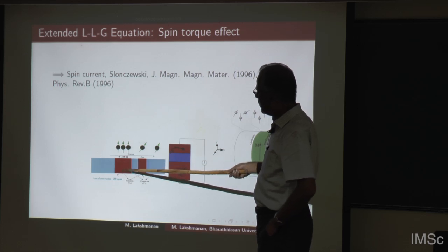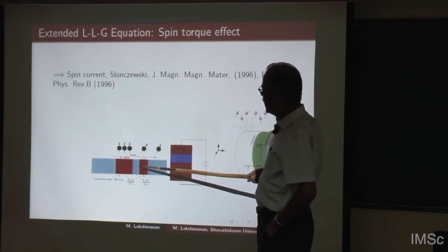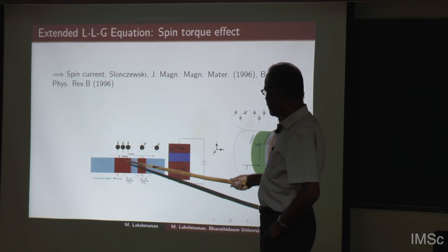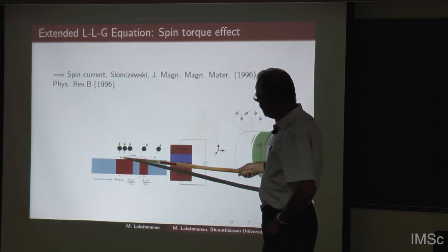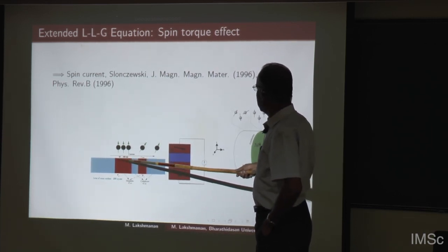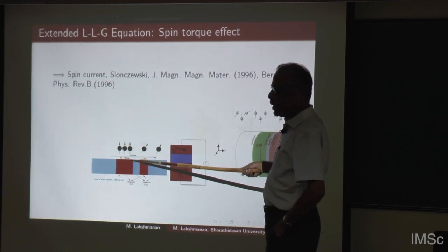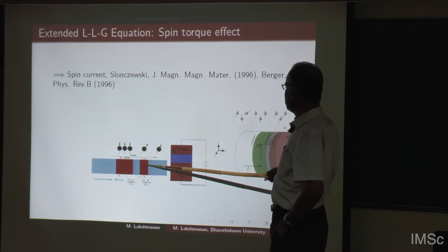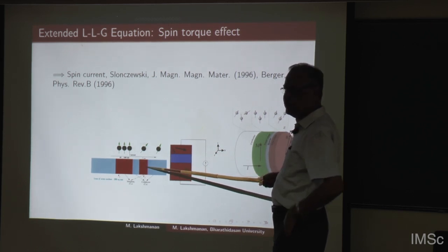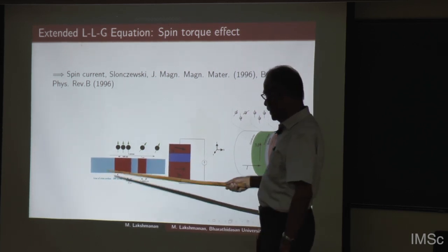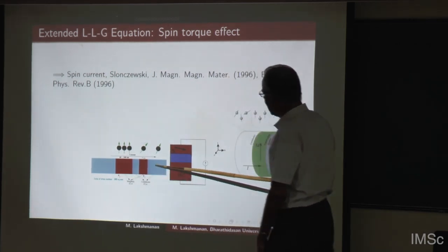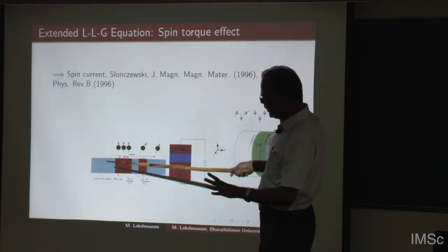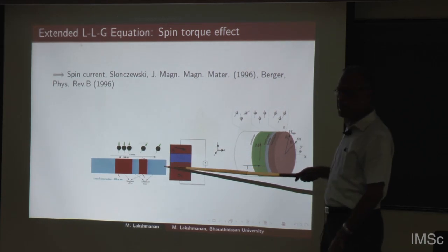So, you have cobalt, copper, cobalt, and this is a nanomaterial of the order of 40 to 100 nanometers, and this is again a small spacer, of the order of 2 to 4 nanometers film size. And then you have the outer conducting materials. So, actually this is a 5-piece nanomaterial.